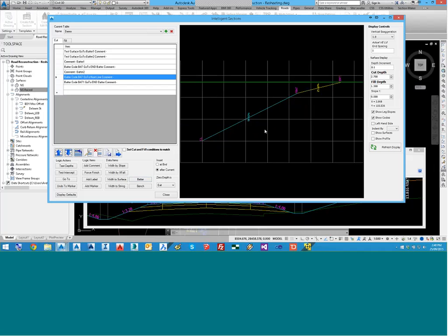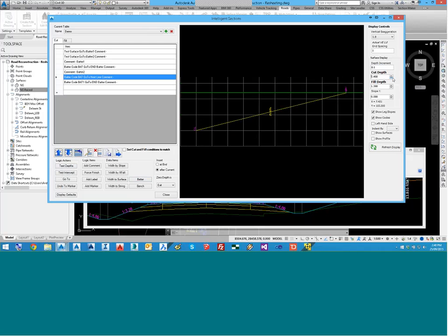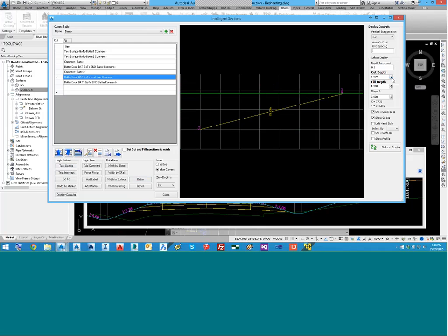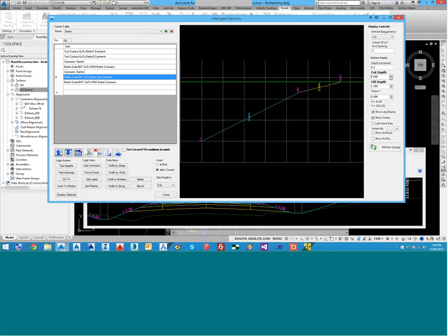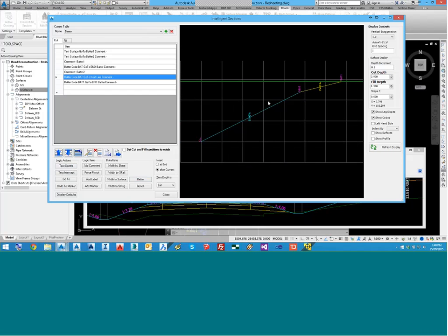All right. This is similar to that dual section one that I set up, I suppose. Other than doing depth checks, you can do slope checks as well in this intelligent sections command. But anyway, if we're not that deep, we go at 1 to 4. If we start getting deep, then the software will put in a 1 to 2 batter, and then 1 to 4 when it gets to within half a metre.